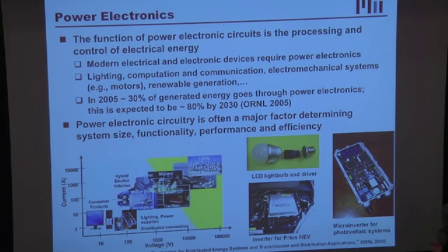And each of those layers of power electronics has dissipation. So you may actually get less than half of the energy coming in from AC that's actually getting to do your Google query for you. And so there's a tremendous waste of energy. And that's true in this example too. In the LED lighting system, somewhere between 10 and 30% of the energy, the AC energy coming in here, never even gets to the LED.